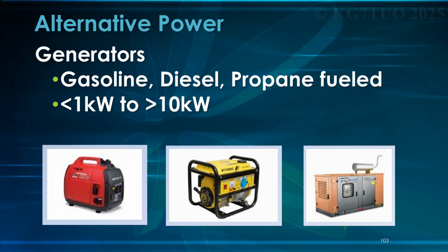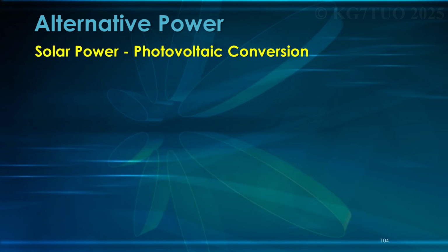I'm not going to run my heat pump, my refrigerator, and the dryer. I'm not going to run the dryer at all. But the heat pump and the refrigerator, yeah, I can run those. Do I turn all the lights on at the same time? No, I'm going to juggle loads. So what do you need? You could probably get away with 2 kilowatts, 3 kilowatts, and run the whole house.